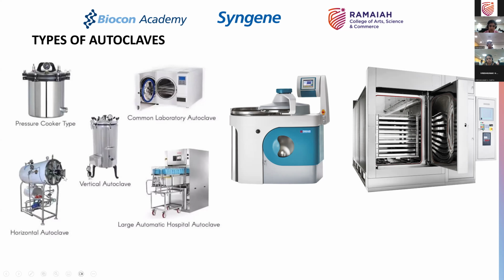It's like trying to load a tray in a circular thing; you can only load it up to a certain dimension. But this was preferred because there were no sharp corners, no 90-degree edges, and as a result the steam distribution was much better. Till people and engineers came out with the design of rectangular chambers, which is what you see here and here. With rectangular chambers, you didn't need to make it completely circular. You could afford to keep the top and the bottom flat and the sides vertical, so you had a proper flow of steam any which way.